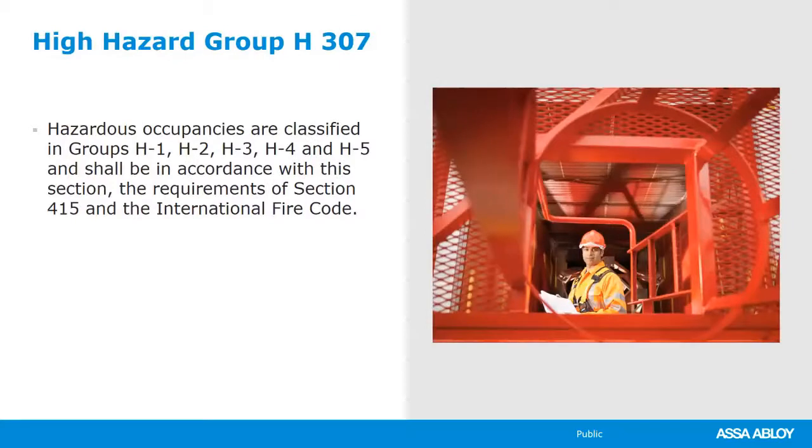Additionally, you could have high hazard, which is a storage room. Maybe they're going to be storing med gas, but it has to be a certain quantity of med gas and how they're stored, what type of canisters, how they're stored within the storage room. But if it is classified as Group H high hazard, then your requirements are more restrictive for the hardware that you select, and exit devices would be required from any high hazard space. It could be any area within the hospital that you're storing materials that are highly flammable or likely to explode. When in doubt, always ask the question.